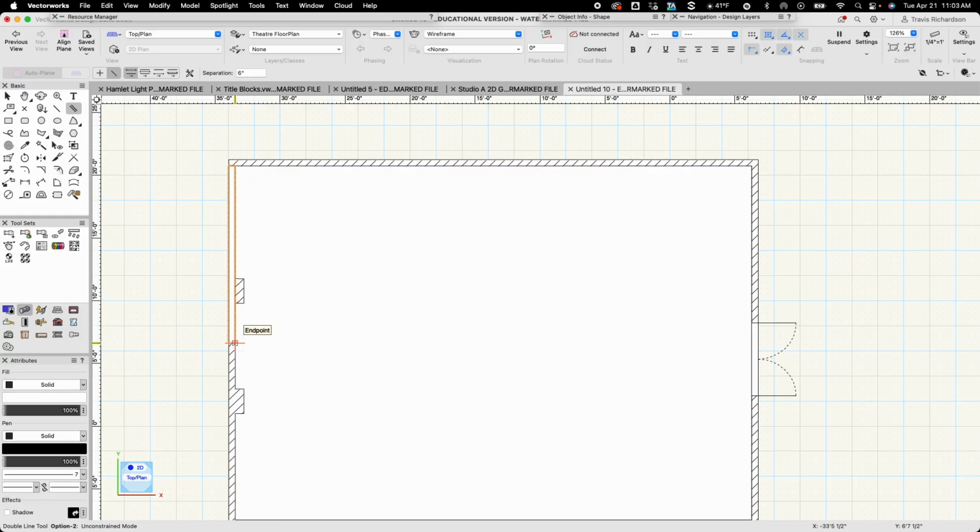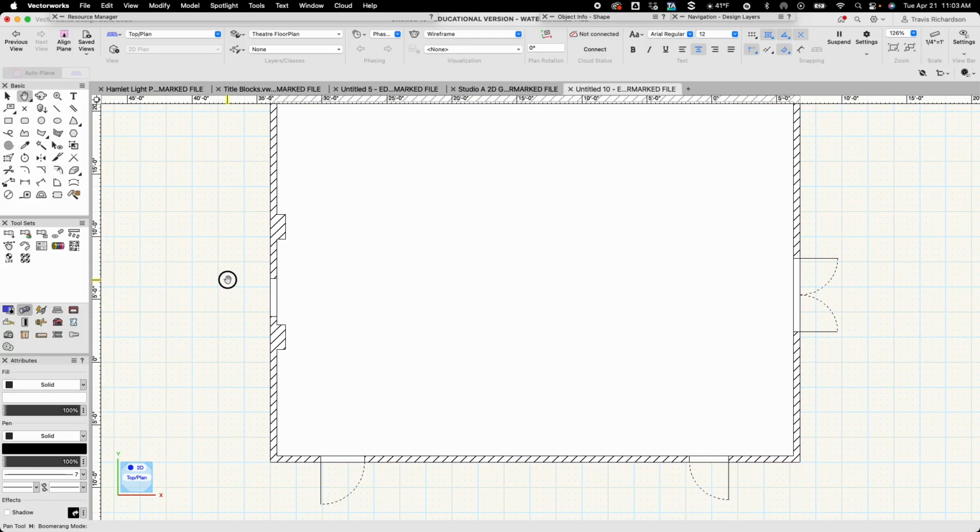And this door is 3 feet wide, so I can click on the bottom right-hand corner of this rectangle I just drew and come down, tab in, and say 3 feet. There's the opening of my door. I'll click on my spacer and get rid of it. And then I need to draw the last door and swing arc of that door.